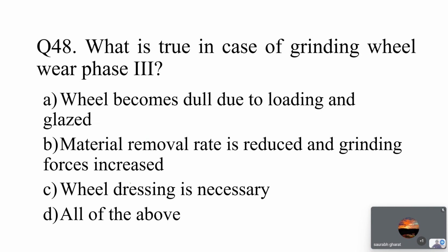What is true in case of grinding wheel wear phase three? What are the options? The wheel becomes dull due to loading and glazing. Yes, it's correct, because due to high wear rate in the third stage the tool becomes dull, and due to loading the chips get clogged, and it glazes due to rubbing action.